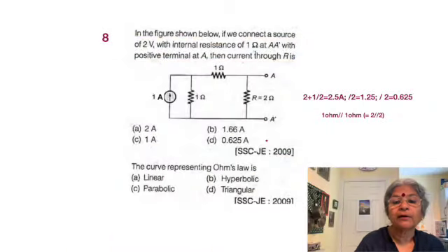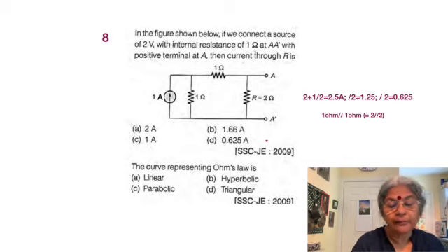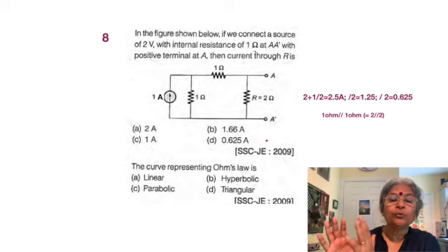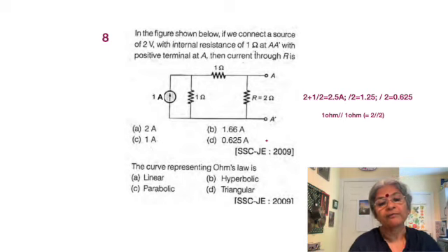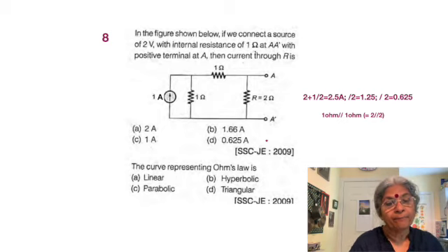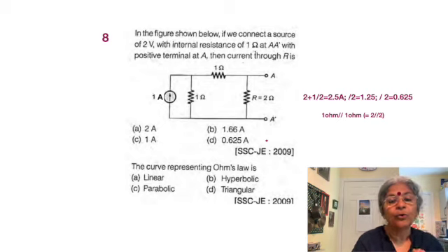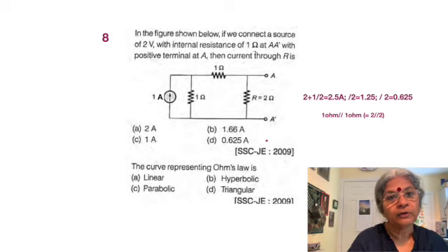Now we are having 1 ampere in parallel with 1 ohm, so that can be a 1 volt source with 1 ohm, and then 2 ohms. We have retained R, the 2 ohms. We are now working from the left side, so now we have a half ampere source with 2 ohms in parallel to it. So now we are having 2 ohms and 2 ohms and another 1 ohm. These two 2 ohms are parallel with respect to each other. That creates another 1 ohm.